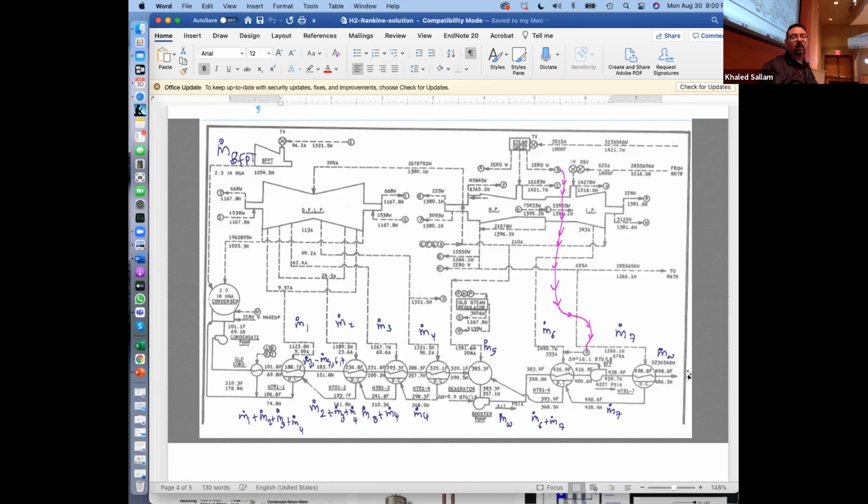So what do I need you to learn from this? Just applying the first law of thermodynamics to a feed water heater, whether it's open or closed. How does the first law look like? Q equal Q. M dot delta H equal M dot delta H. Or sigma M dot H in equal sigma M dot H out. That's another way to see it. When there are multiple inlets and an outlet, maybe it's easier to just say all coming in equal all leaving.